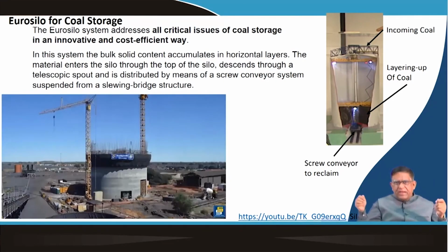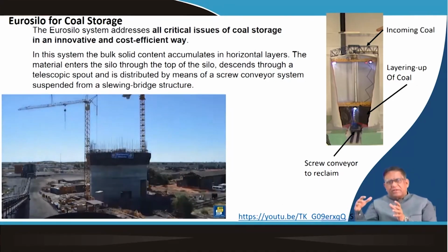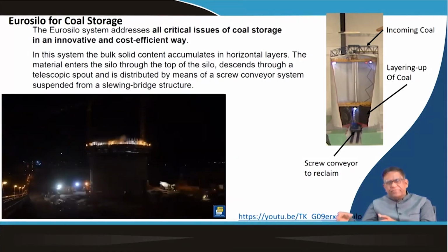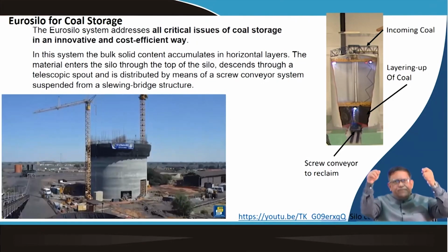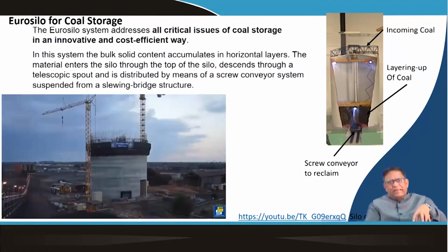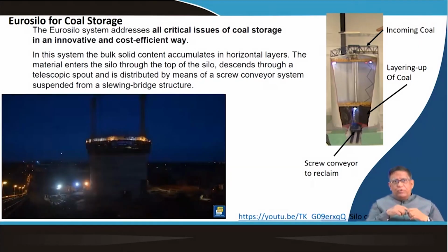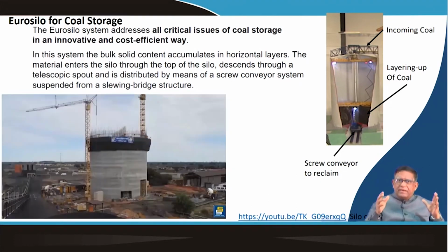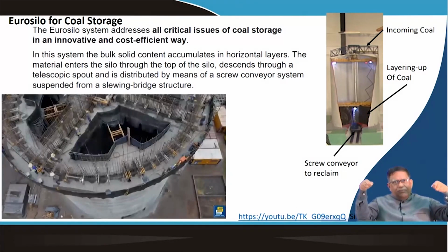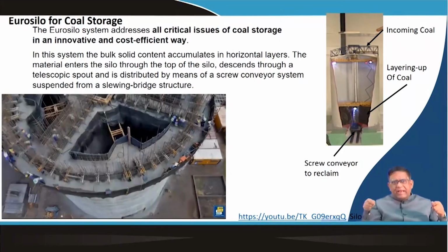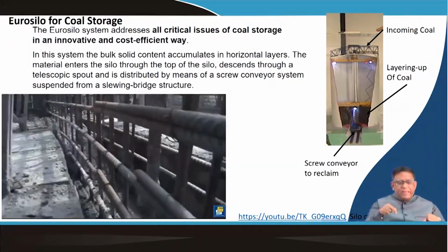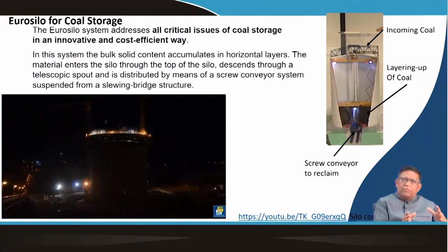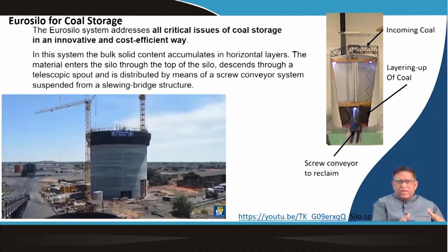You can imagine the tower head, that crown, is manufactured at the bottom, then lifted with a crane and placed over the tower. The type of wind load that will come and the stability that must be maintained matter, because it is suspended with a wire rope and crane and must be placed very precisely on top of the silo tower.